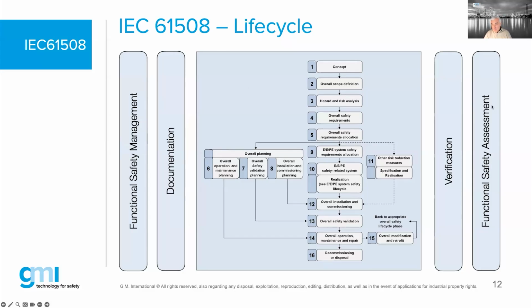And again, depending on what level of SIL the interface is supposed to be used in, they need to prove evidence by the 61508 requirement that if it is a SIL 1 suitable device, then an independent person needs to make that assessment. In other words, to make that expert judgment to prove evidence that this equipment can maintain a certain integrity to reach a SIL 1.